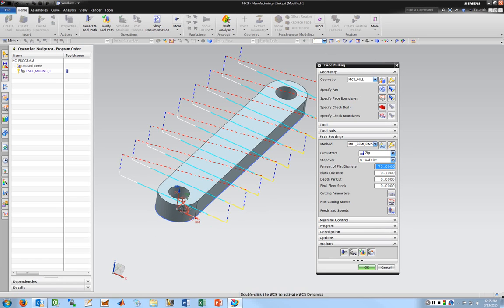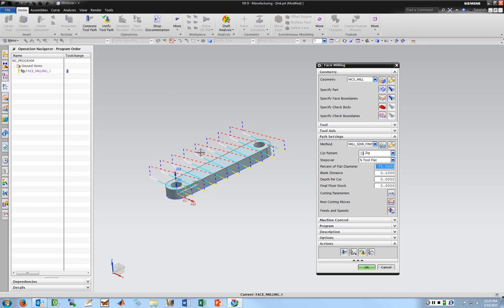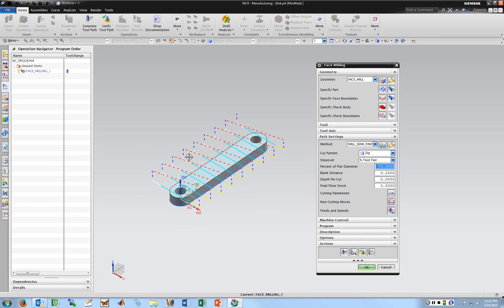So what I could do is rotate my parts so that this would be the X direction, or I could rotate my machining coordinates. So if I actually wanted to correct that, I'd have to rotate that. I just wanted to do it this way so you could see how if you don't have it rotated correctly, you could get something that you don't really expect.